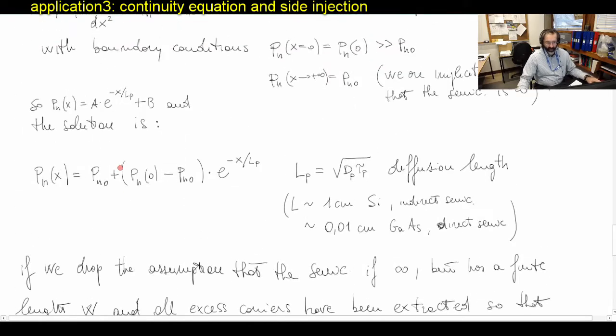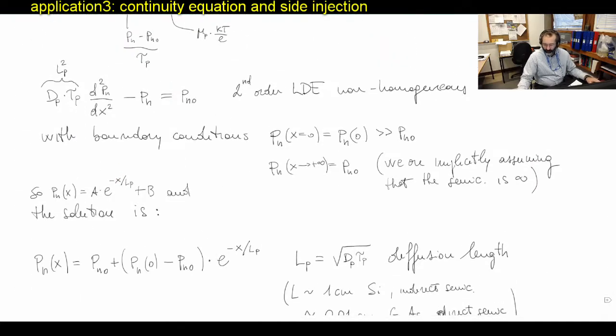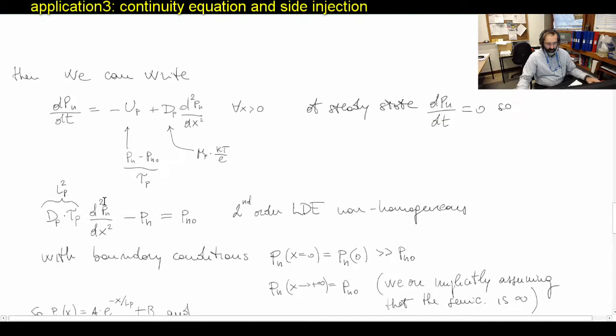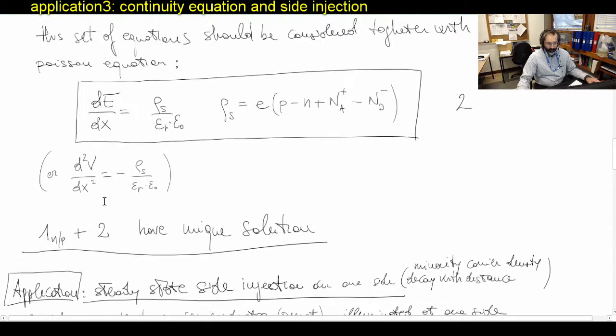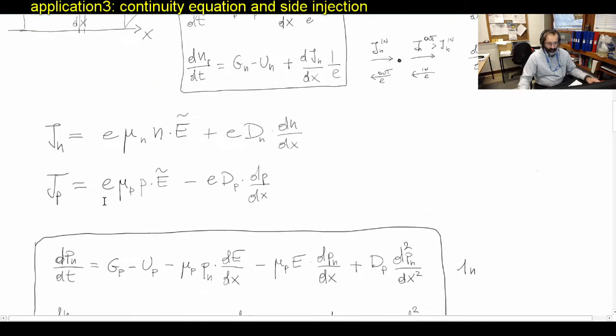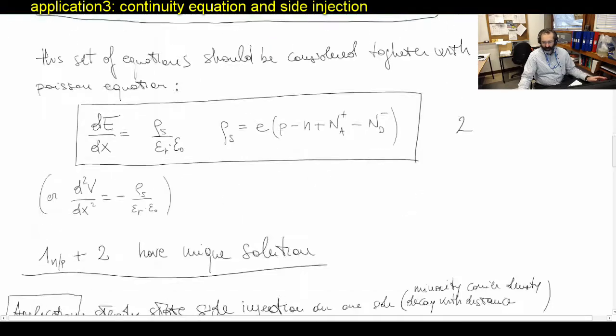Remember that J, in the case of P-type carriers, is made of two terms. We can throw this one away because it is related to the presence of an electric field, and we have no electric field right now. So J is simply given by diffusion, if there is any J, and so we can use this term to calculate J.